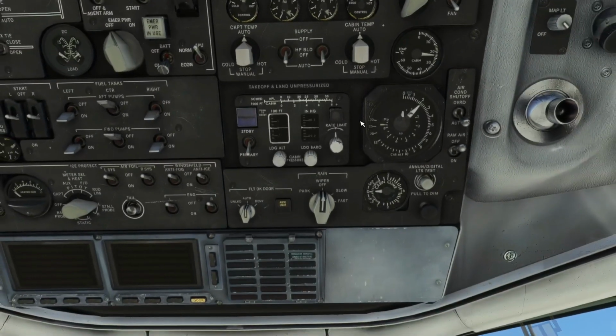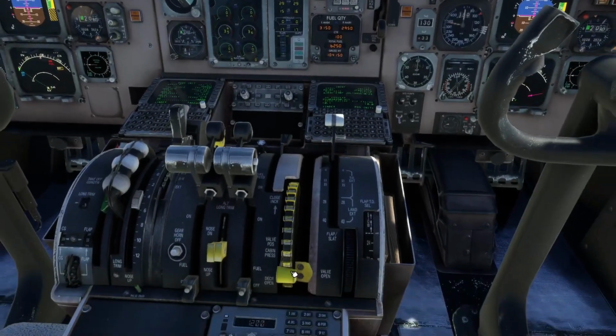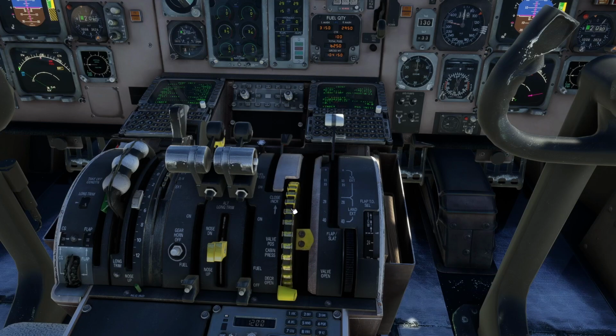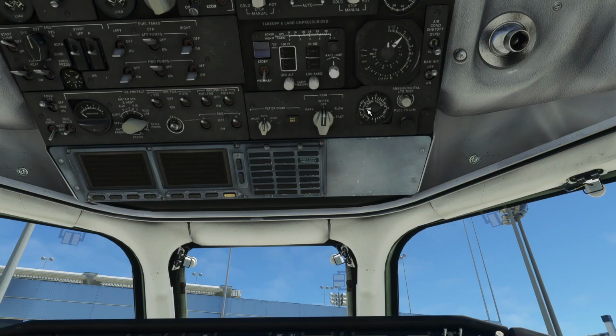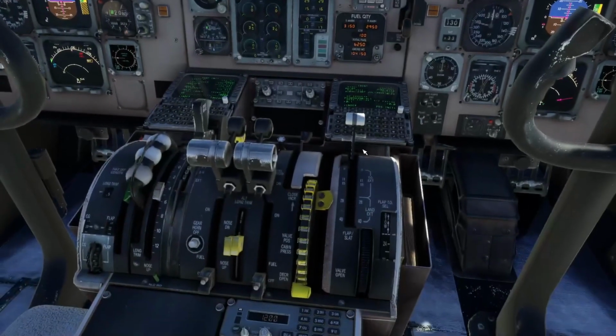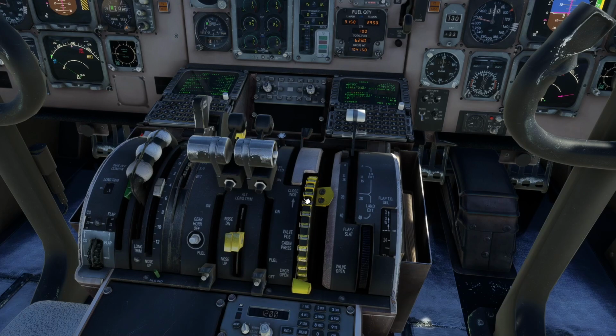Okay. If you do have to go into manual mode and manage your pressurization on your own, use this valve sparingly. It wants to kind of run a little bit, even though you hit it nicely, and so it's got some inertia to it. And then you'll want to hit it and then just kind of watch the cabin altitude climb or descend. Remember, opening the outflow valve is the equivalent of climbing the cabin because you're releasing the pressure, and closing the outflow valve is descending the cabin because you're allowing the pressurization to stay inside and pressurize to normal sea level pressure.